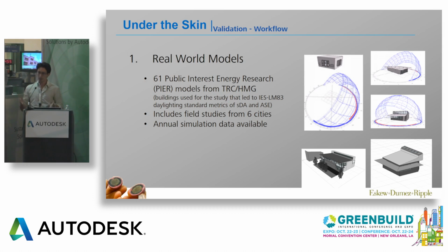And so they're allowing us access to that data set so we can start to build Revit models of those spaces, run the comparisons, and then also compare them to the Radiance simulations so we can get some really granular comparisons of real-world energy simulations to the new Revit tool. You can see that these are a little bit more complicated than the simple box from the NRC study, and they actually have skylights, there are clerestories, they're representative of actual spaces out there in the real world. So we think that adds another layer of confidence to the accuracy of the tool if we get them to line up, right?